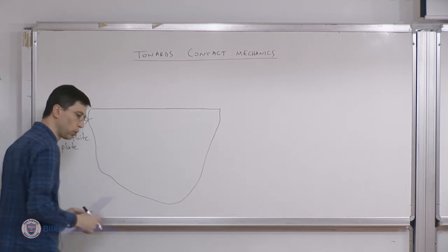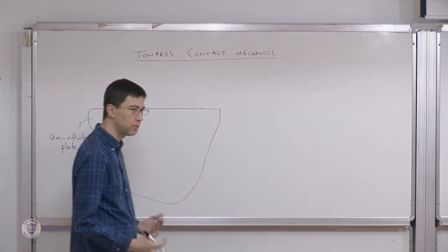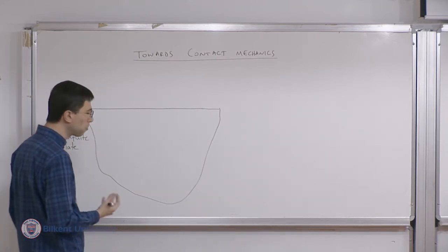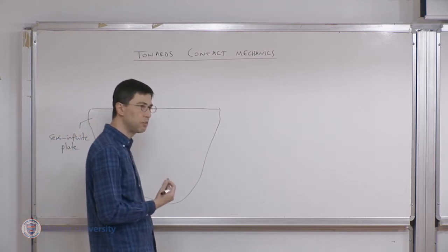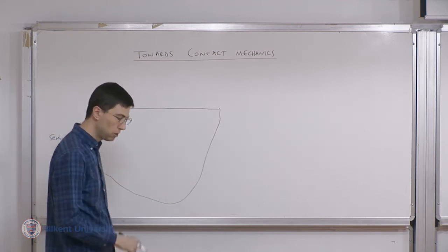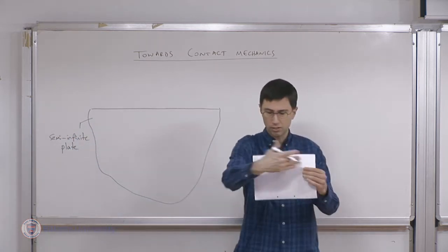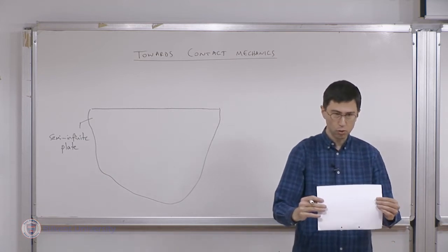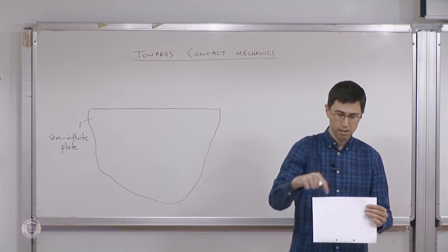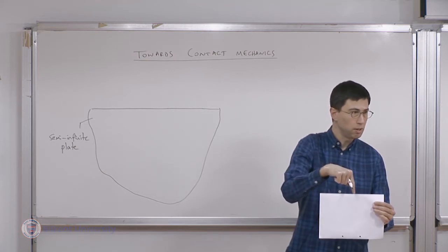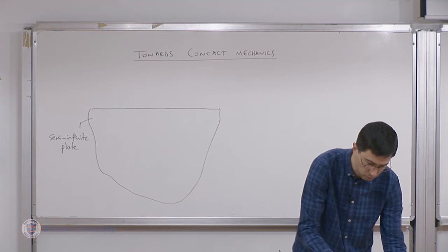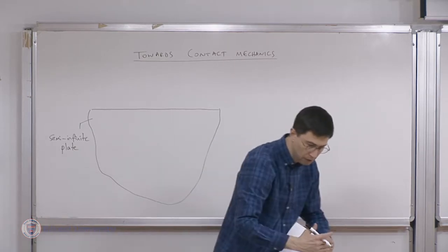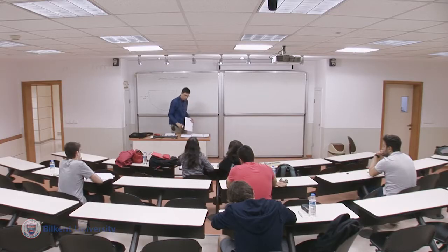So again, as usual, we're going to solve this problem in a unified setting where we might have plane stress or plane strain, although this problem eventually is more natural to think of in terms of plane strain than stress, because if it's plane stress, then it means I'm looking at a very wide and very deep object that is also very thin. And if you try to load such an object with a point force, what will happen is we will just buckle. So that's not quite a natural thing to do. We want to have the object very broad, and I want to impose a point force.